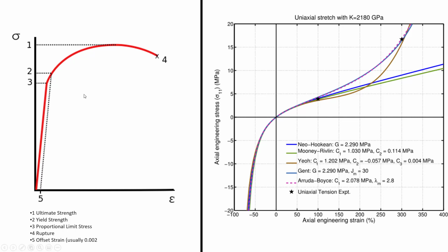SolidWorks simulation, or SimXpress, only focuses on the linear elastic portion, the linear portion of the curve here. It totally ignores the plastic portion, okay? So even if you get above yield stress, it's just going to keep following that linear portion up to infinity, all right? Just following the linear line. That's one of the requirements, or one of the limitations of SimXpress.